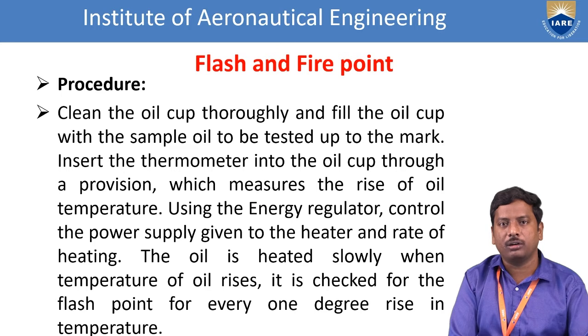After that, we see how to determine the flash and fire point by the required procedure. First of all, clean the oil cup thoroughly and fill it with the sample oil to be tested up to the mark. Insert the thermometer into the oil cup through a provision which measures the rise of oil temperature, and using the energy regulator, control the power supply given to the heater and the rate of heating. That means the oil is heated slowly. When the temperature of the oil rises, it is checked for the flash point for every 1 degree rise in temperature.